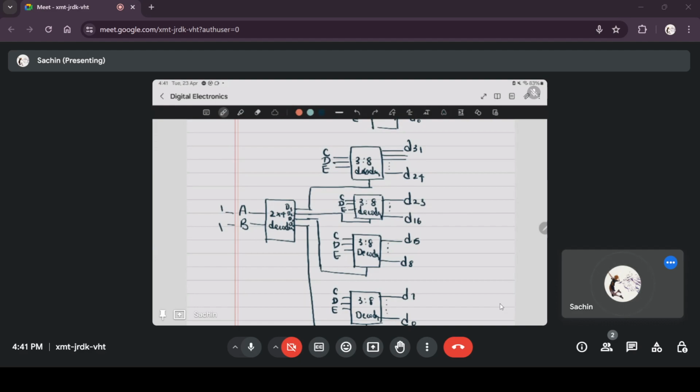Instead of a 5-input AND gate, if you have only 3-input AND gates, then for 3 of the inputs you can give 3 inputs to the first AND gate and 2 more to the second stage of AND gate. So if you wanted to have a 5-input AND expression, then you would need two 3-input AND gates.